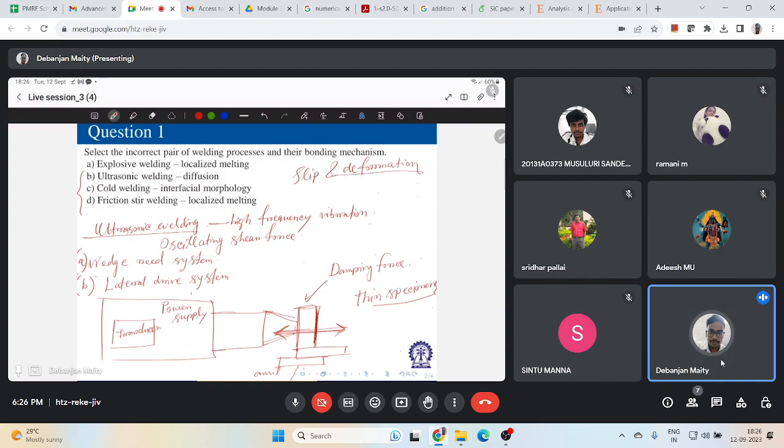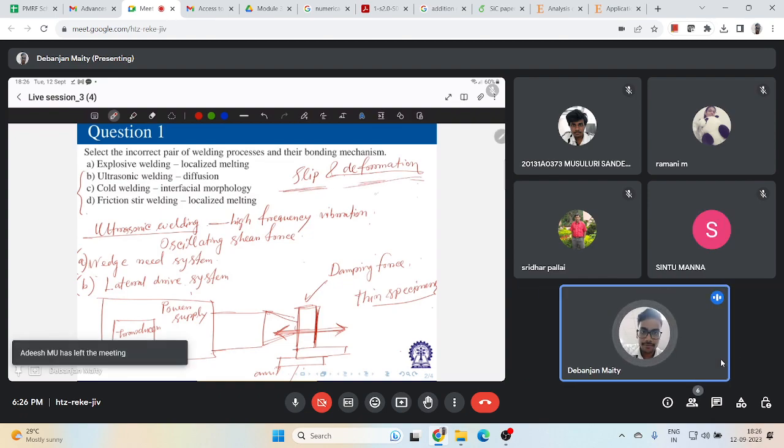You are basically moving the dislocation defect, and there are two kinds of dislocation. I hope you know edge and screw dislocation. So you are deforming the workpiece, interfacial slip is happening, and plastic deformation is happening, right? And here also the temperature is influenced by the power of the sonotrode, by the clamping force, and also by thermal properties of the material like conductivity, specific heat, even density.